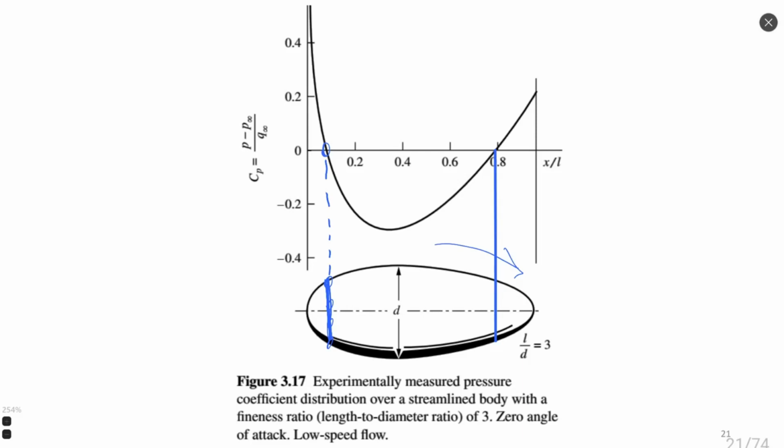So if we have a main wing, let me draw here on the side. Okay, let's imagine this main wing here. It's not having zero angle of attack. It already has some value, some inclination, but small, as we know. Very small angle of attack. So such a compensation can be easily made when we install Pitot tube. For example, we install this Pitot tube horizontally, or we apply some coefficient like trigonometric function to calculate. But usually we can adjust just the position of Pitot tube, I think, and no need to recalculate.